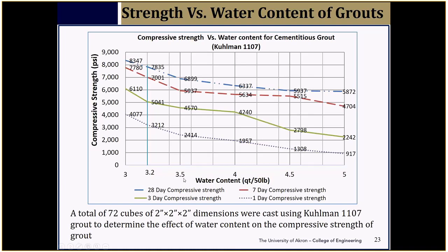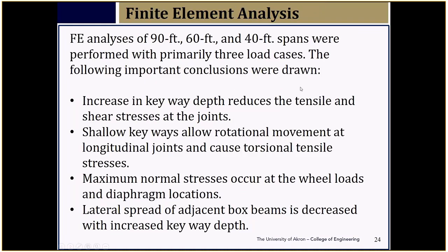So that's the problem, and that's the practical problem. Nobody has any bad intentions, but it's just a practical problem. You cannot place the grout with the amount of specified water. Then we try to understand what kind of stress conditions exist in the joints. So are they just functioning like fillers, or are the joints functioning in a way that we can consider as load transfer? And in order to understand the stress condition in the joints,